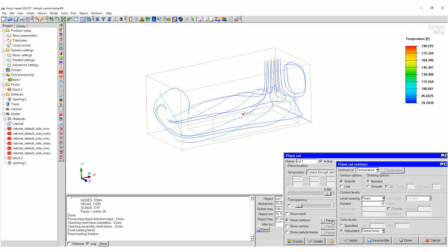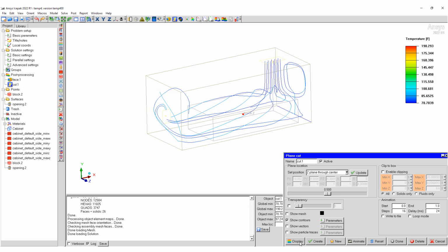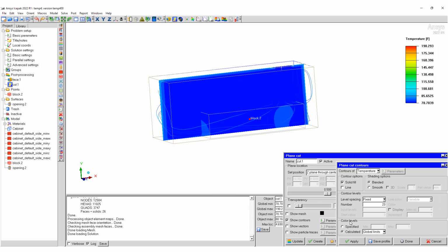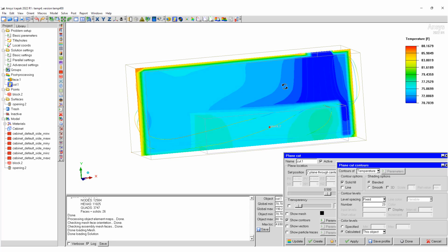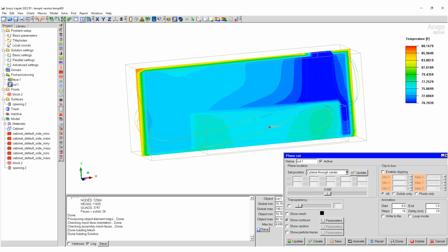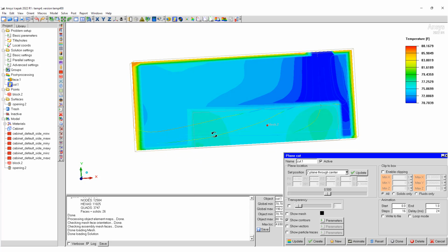We can create a velocity, a temperature contour through the Z, sure. And we can look at the local limits of this. So the outside is something like 100 degrees, 120 degrees Fahrenheit. The inside is 80 degrees. So not doing a great job of cooling our package there. So 1,000 watt is not quite enough. 10,000 watt is more than enough. So the real benefit is somewhere in between.